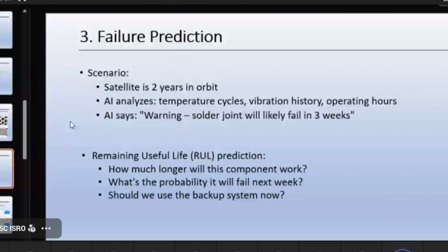We have seen the history of the transistor: if it experiences thousands of temperature cycles of this temperature swing for these many hours at this functional level, we found that the functionality of the transistor has gone down. Let's say degradation has started. Or let's say the temperature is not this much. If the temperature range is less, if the timing is less, if the functionality percentage is less, the life is more. So this way we know that the predicted lifetime of the component is this under these conditions.